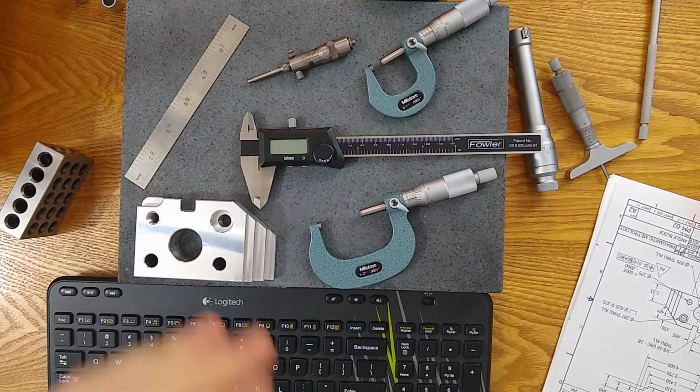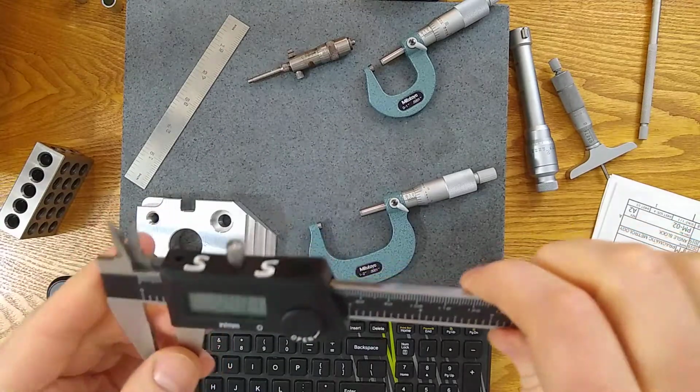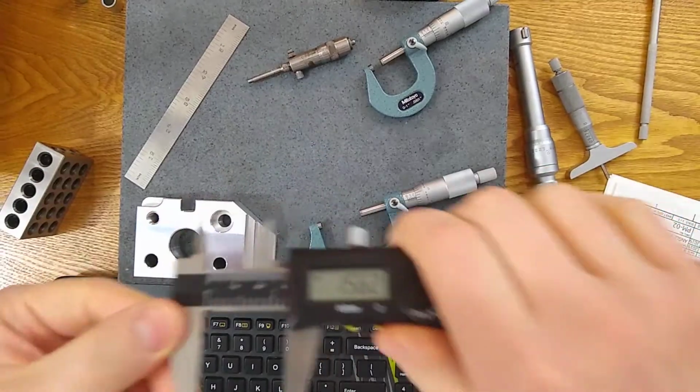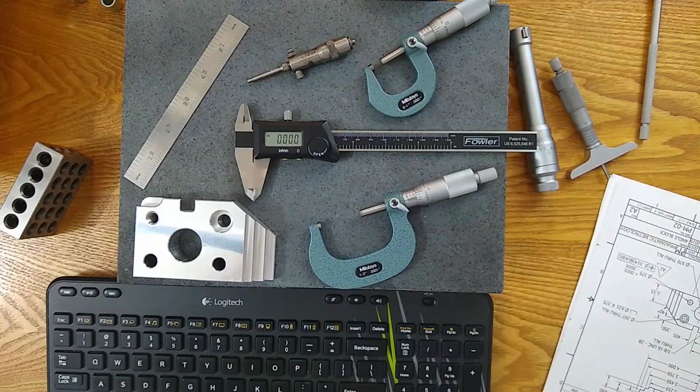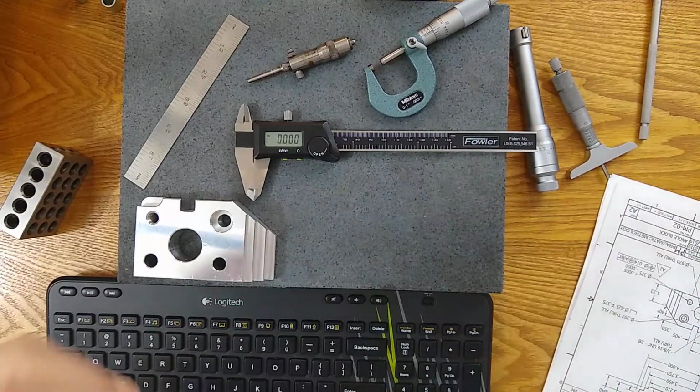But if you have something like a caliper that has kind of a big accuracy issue compared to many of the other gauges I've talked about, sometimes a caliper is not accurate enough, where the accuracy of that caliper and the tolerance zone are just too close to each other. You don't want to use it. So you're considering that. Once you have considered the tolerance zone and the gauges you have, you make a selection.